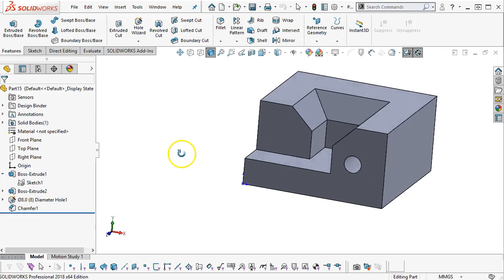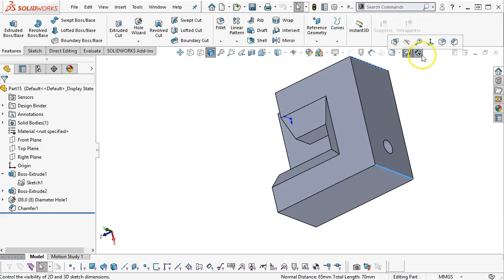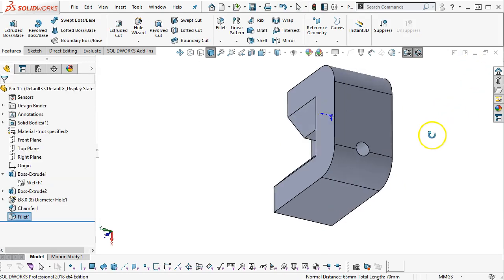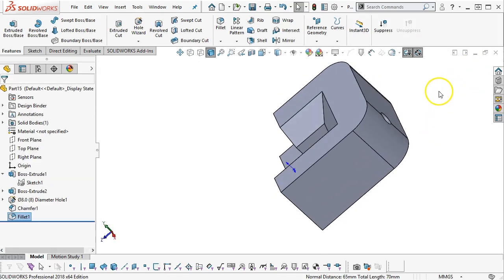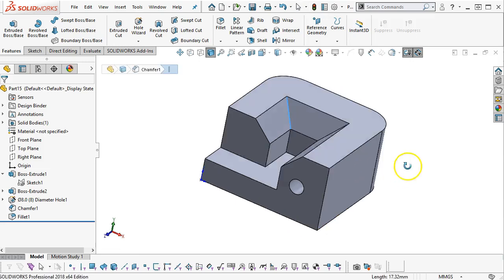Okay, so looking pretty good up till there. Radius of 14 in 2 places. And we'll go to fillet. 14 millimeters. Comes up right to that back edge. So a little bit of deformation on the edge, but largely that's going to give us our shape. All right, so we talked about this mitered inside edge.